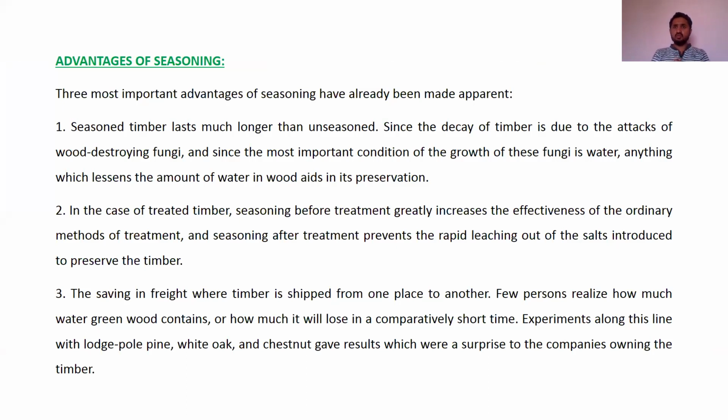So what is seasoning actually doing? What we are doing in seasoning is reducing the water content of the timber, or drying the timber. If we don't do seasoning, then definitely the moisture content in the timber is there, and it will lead to the attack of fungi, and it will destroy the properties of the timber. Also, if we do the seasoning, all the properties of the timber will get enhanced, right? All the properties of timber can be improved because of seasoning, except shrinkage. Keep that in mind. So that's why the seasoning should be done.